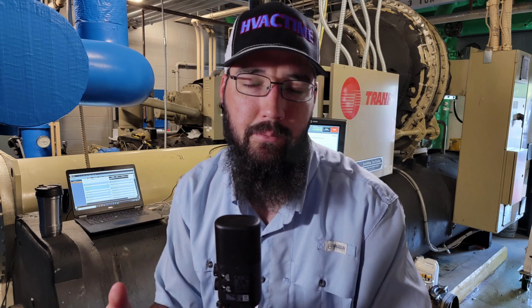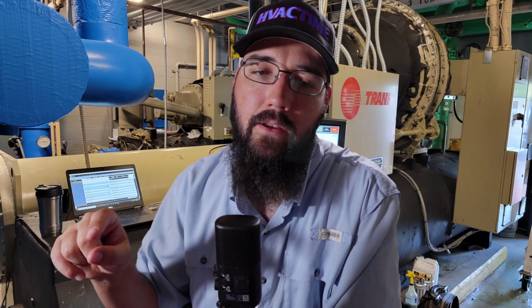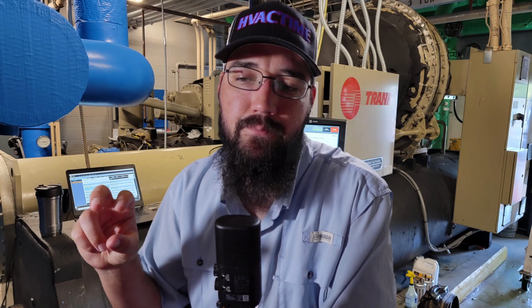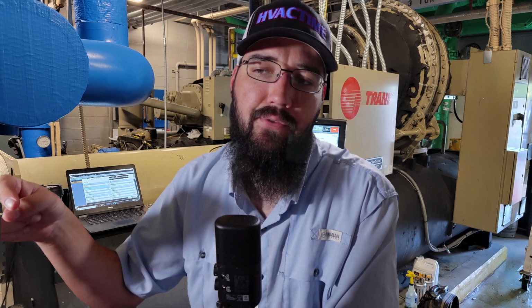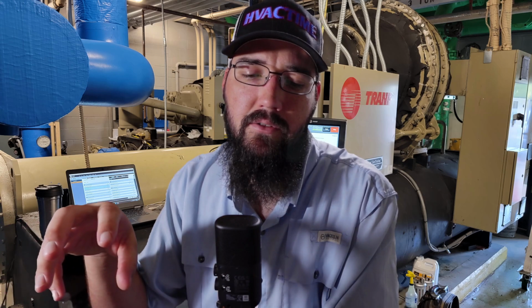And this is a screw machine, by the way, if you didn't know. So then when it comes time to get that oil to return, we will close off the drain line and the vent line, and then we will open a hot gas line from the condenser and use that to physically push the oil laden liquid refrigerant back up into the return line up into our compressor. And there's an actual orifice up there